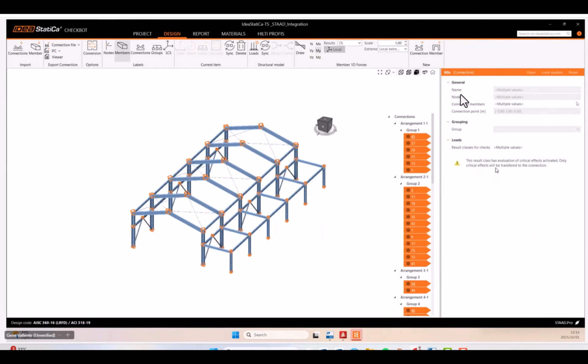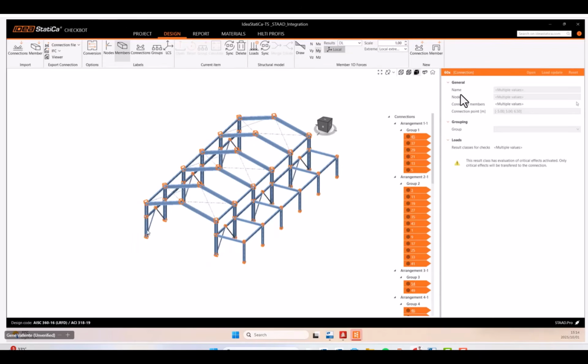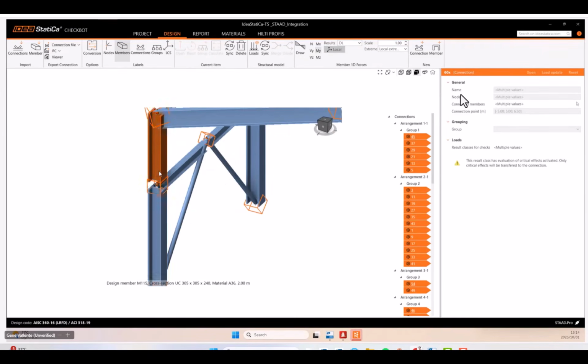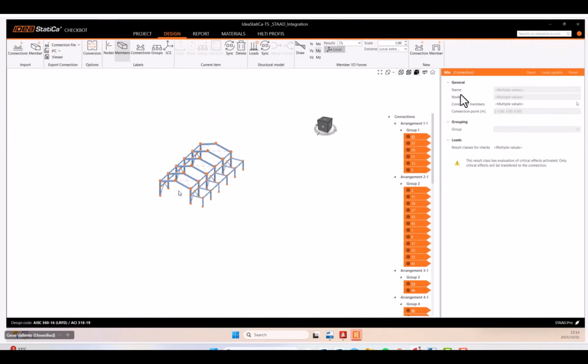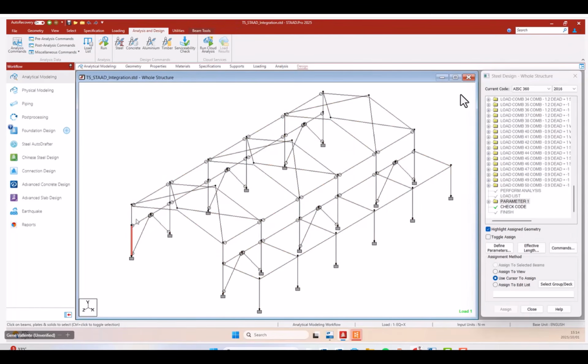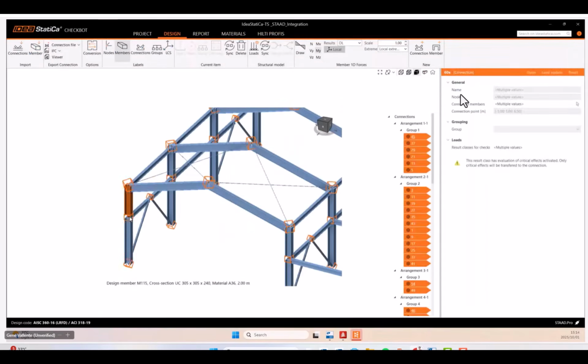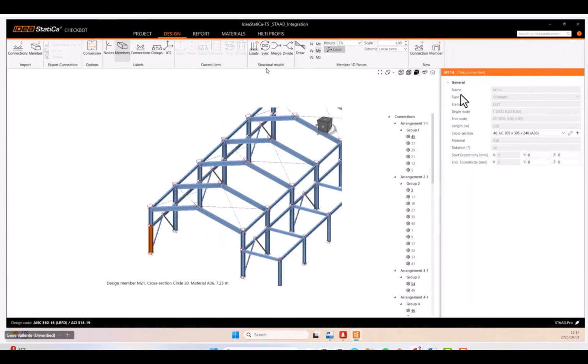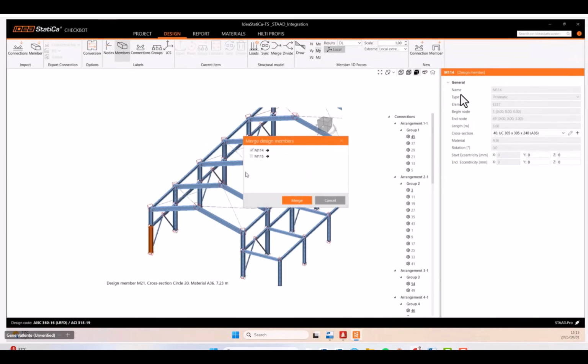So this is basically grouped for now, but in our case, we still need to do some adjustment right here, no? You see, in IDEA Statica, it captures everything STAAD.Pro has provided. For example, in STAAD.Pro these members are modeled node to node, but in actual conditions this can be a continuous member. So we have the option to merge these members. All we have to do is click on merge.